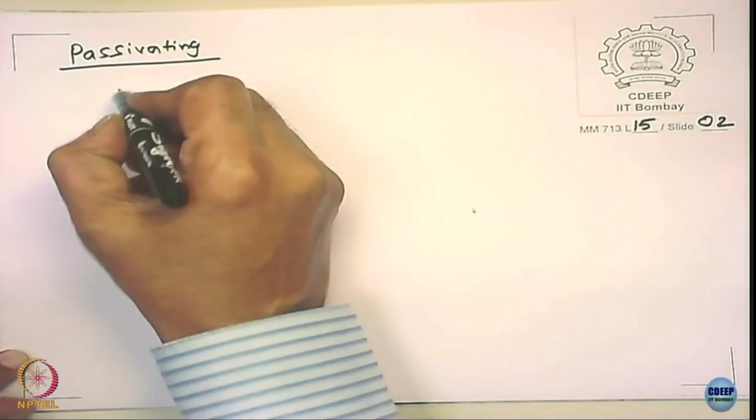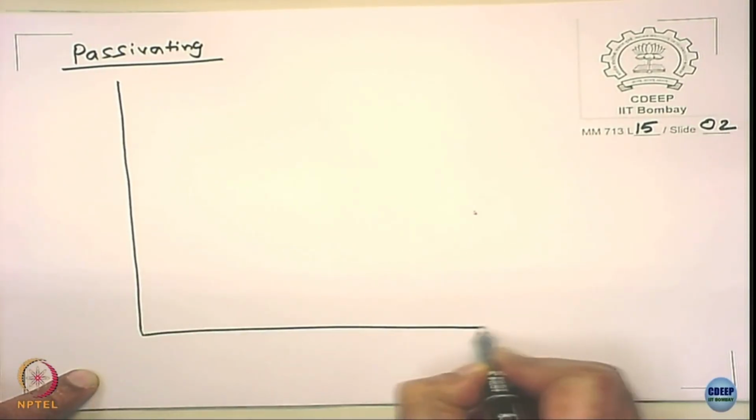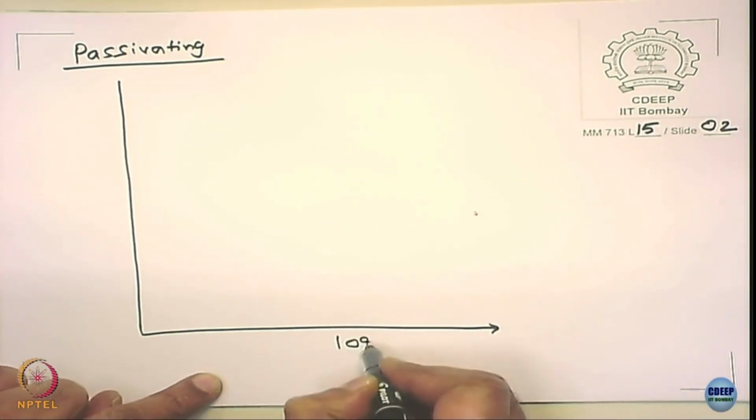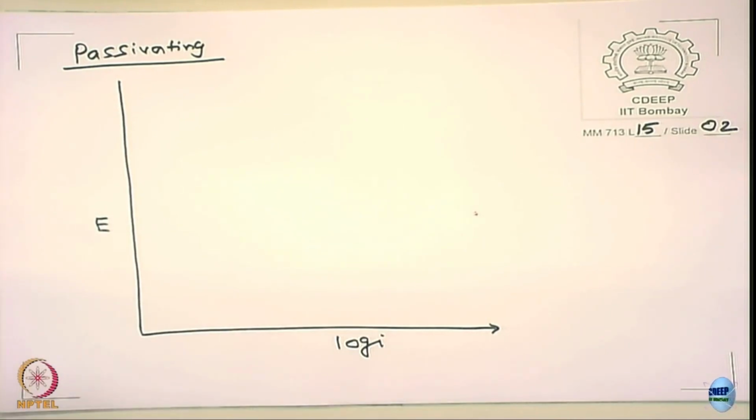The passive systems are, can you give an example of a passive system? Stainless steels, maybe in sulfuric acid, okay, titanium cannot be this. Let's take the case of a stainless steel in acid solution. It is deaerated, it is not aerated. So what happens in that case? It undergoes active passive transitions. We have seen this somewhere before, but it's a different way of interpreting it today, okay.